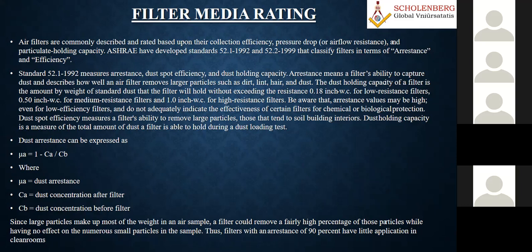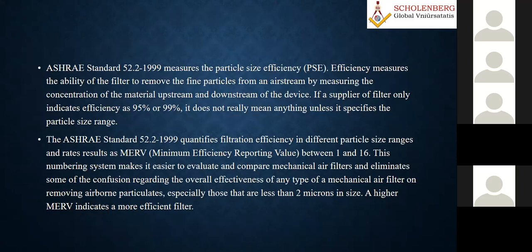So this is the definition. Arrestance can also be expressed by a simple formula, the details of which are given there. This is a filter media rating. On that basis they calculated, and they have also measured the filters by what is called PSE, particle size efficiency. The efficiency measures the ability of the filter to remove particles from the airstream by measuring the concentration of the material upstream and downstream of the device.